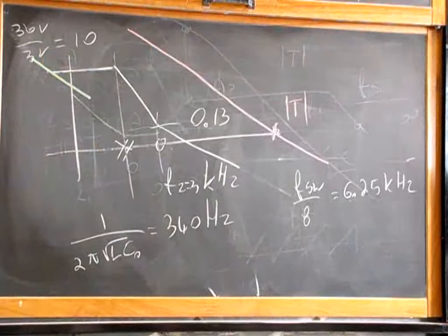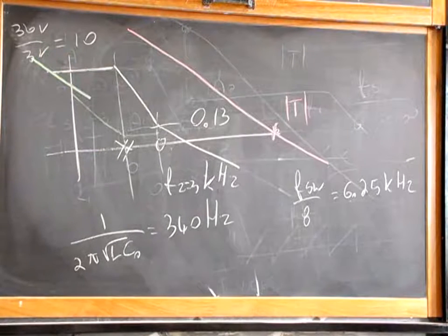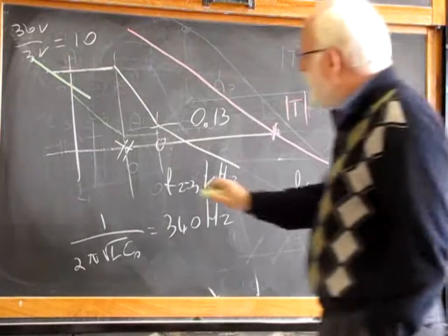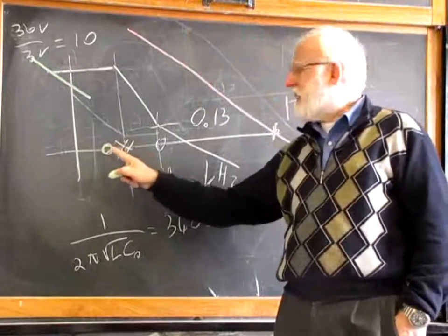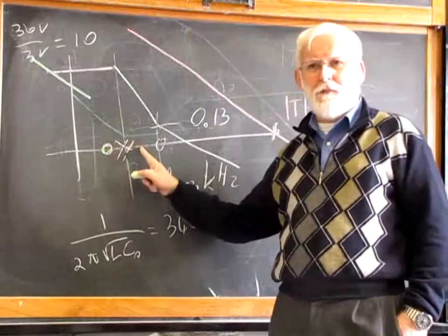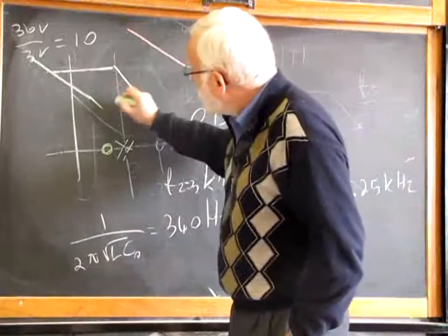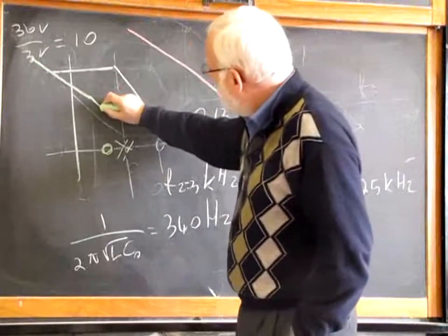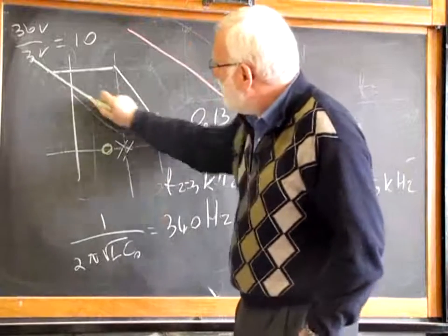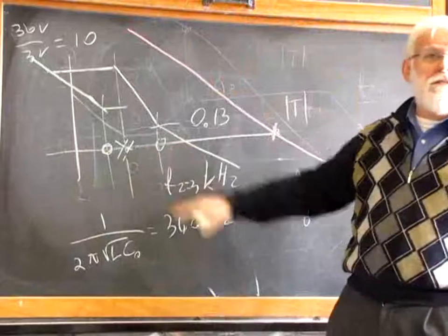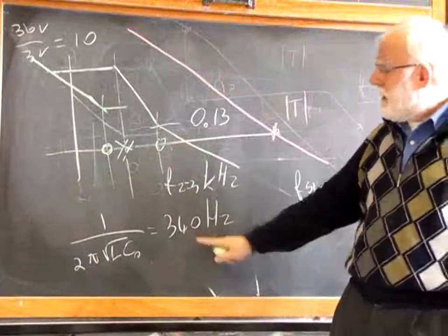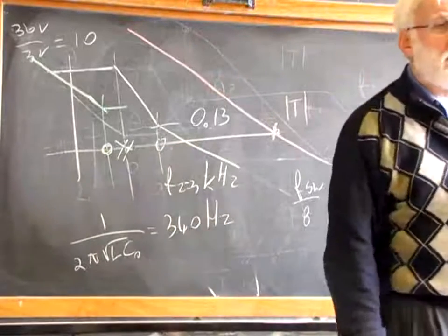It starts with an initial slope of negative 20 dB per decade, comes down, and at this frequency, a factor of 2 before my complex conjugate poles, I set in the first zero. And the first zero is given by the pole frequency divided by 2. So 340 Hz divided by 2 is about